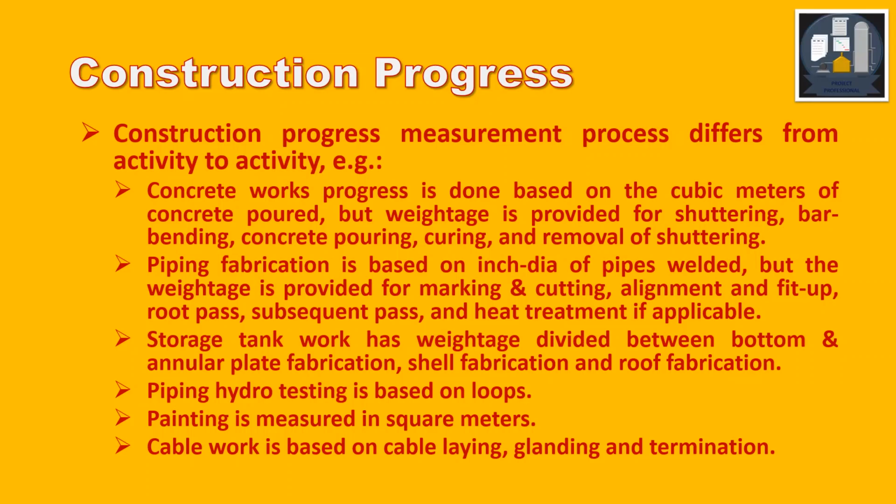In the storage tank work, weightage is divided between bottom and annular plate fabrication, shell fabrication, and roof fabrication. Within the bottom and annular, it is bottom and annular plate. Then in the roof fabrication, it may be the roof structure if it is a fixed roof, and the roof plates. Then in the shell, there are different shells, and the weightage is similarly broken down for each shell.